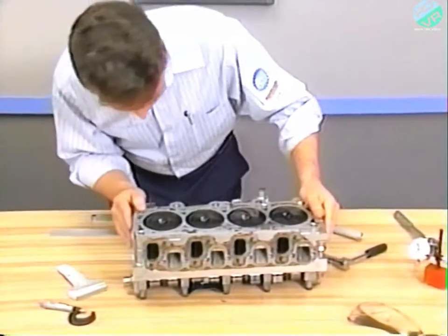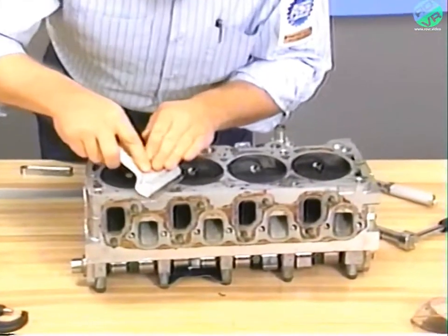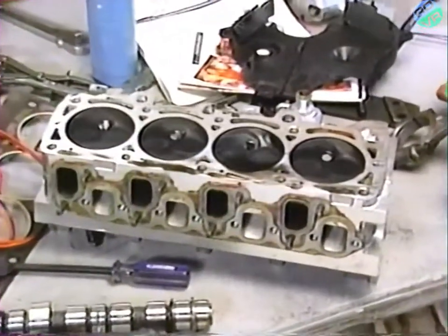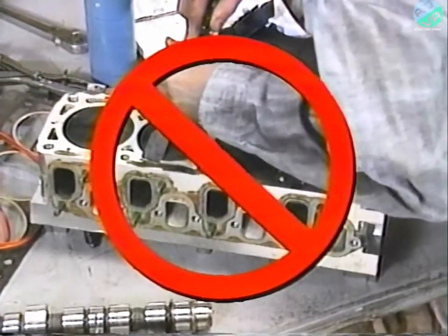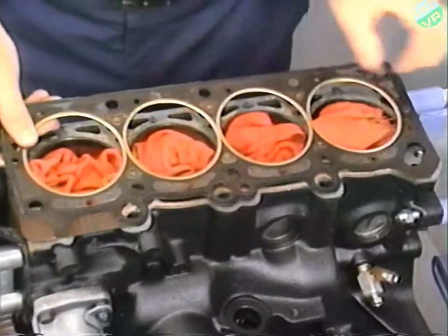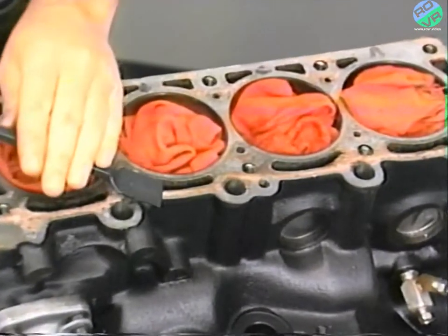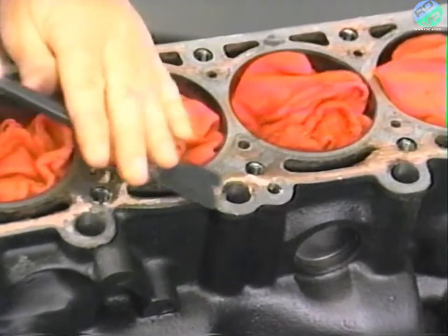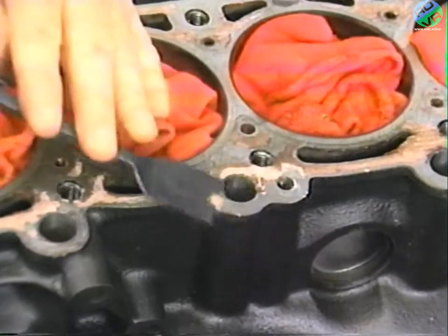First, check the material of the cylinder block or head that you're cleaning. If it's aluminum, you must only use a wood or plastic scraper. Never use a metal scraper on aluminum. It could leave a gouge that no gasket could ever seal. If the block is cast iron, it's okay to use a metal scraper, although it pays to be careful no matter what kind of metal you're dealing with. The sealing surfaces on even cast iron blocks can be damaged by overly vigorous use of abrasives.